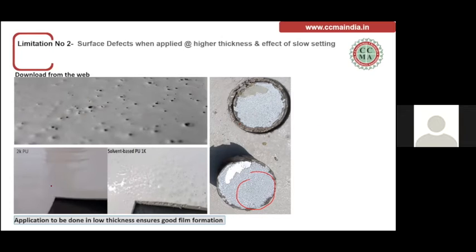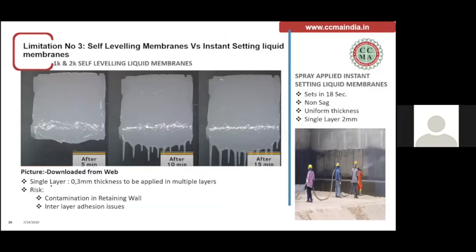But if we see that, we have more flexibility in self curing systems, hand applied and spray applied two component waterproofing systems, which form the film in a single go. So you can develop a film of 1 mm, 2 mm, 3 mm in a single layer. At the same time, the film formation is better. Now, talking about another thing, the application on the vertical.